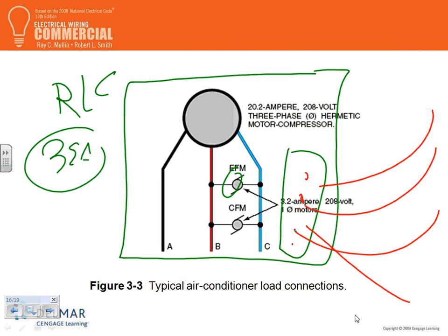I was just wondering about the control. The control, there will be a controller over here. All the wires that you need to control this equipment will be pulled to termination blocks, and I identified where you bring sensor 1, sensor 2, thermostat 1 and 2. You pull them all into that termination box based on, obviously, how the system is going to be controlled. And then you program that control box to get you heat and cool and so forth. That's as far as I can get there.